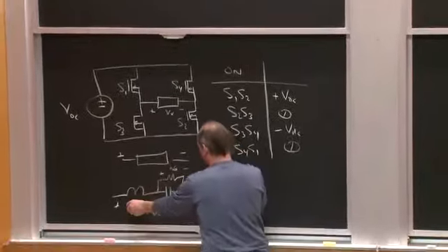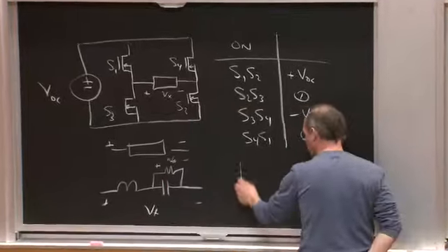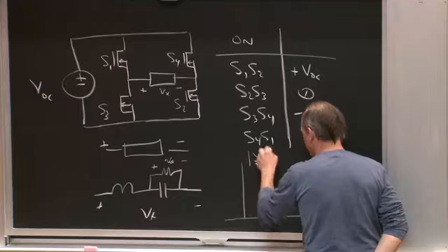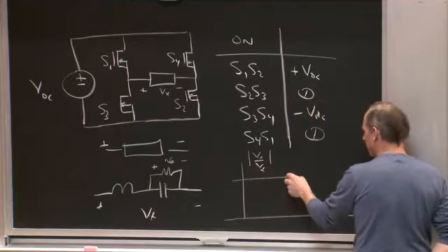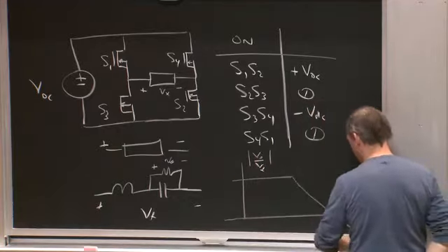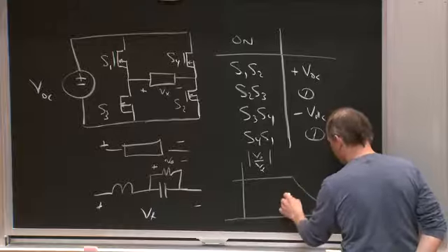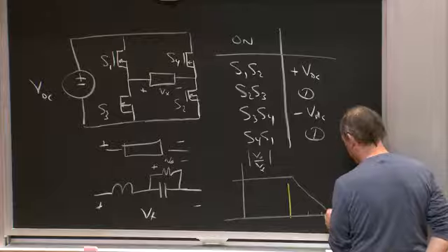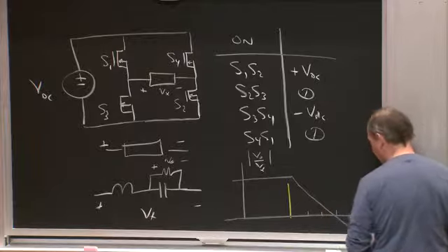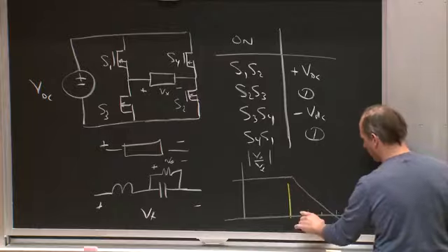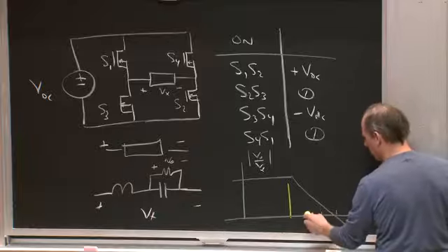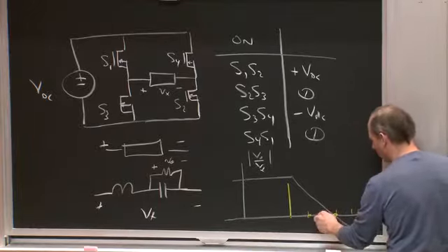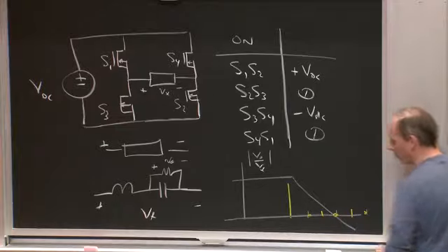So if I think of the transfer function from Vx to Vo, so magnitude of Vo over Vx, right? Ideally speaking, there's going to be some kind of low-pass filter where I want to put the fundamental here, so it's in the pass band, but 2, 3, 4, 5, 6, etc. I usually only want this component, and I would like to filter everything else. We can get rid of these by the half-wave symmetry, and then it's just a question of what about third and fifth and so forth, right?